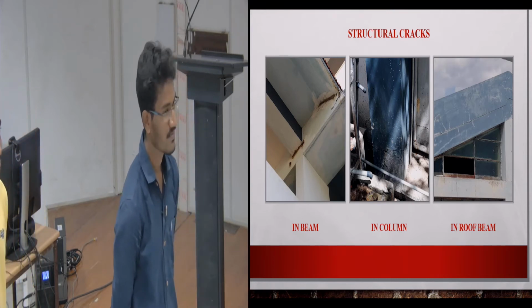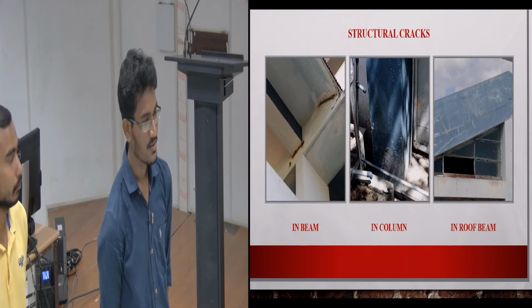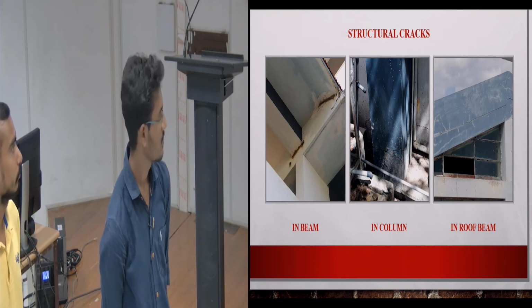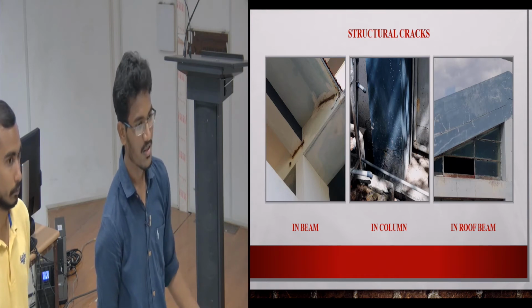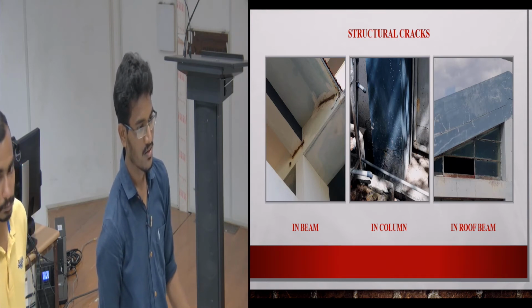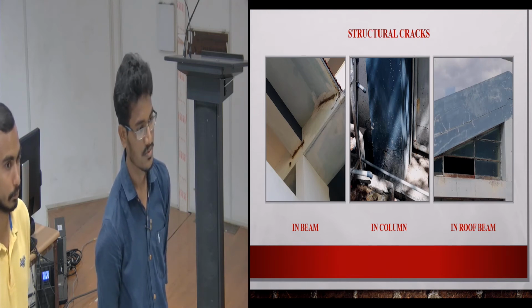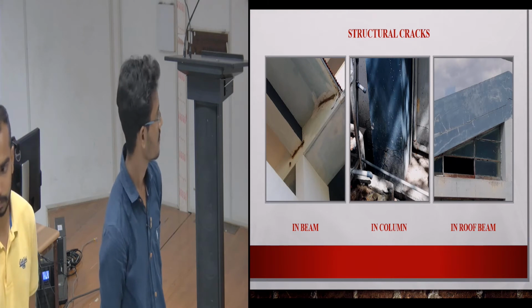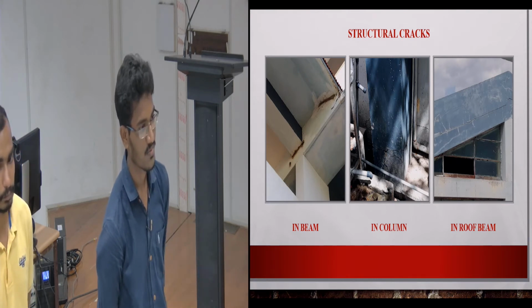And also, if it's actually compression, you should see the floor slab damaged in some way, like a punching shear. You should see the slab has some damage too. So this is all a construction issue. Same thing with the horizontal line. I bet if you crack the concrete, you'll see corroded rebar.